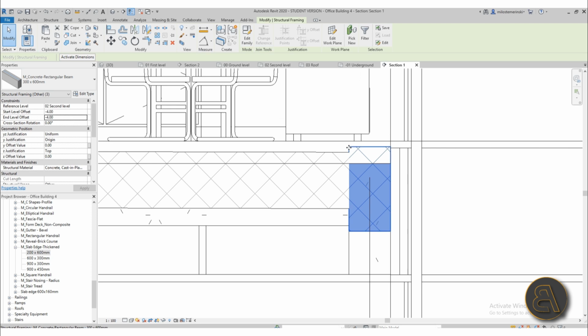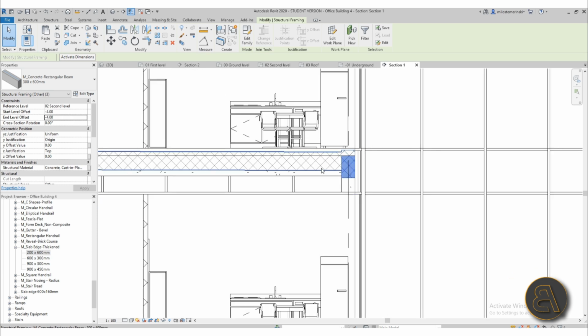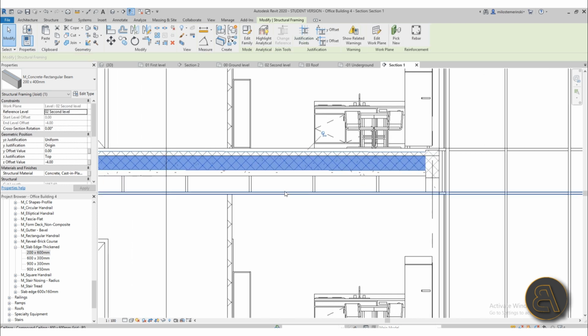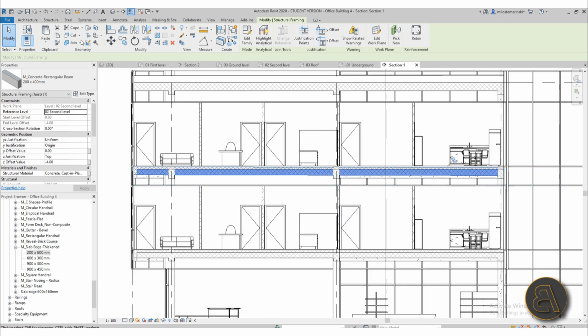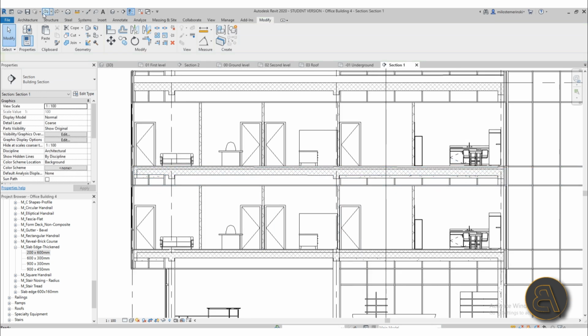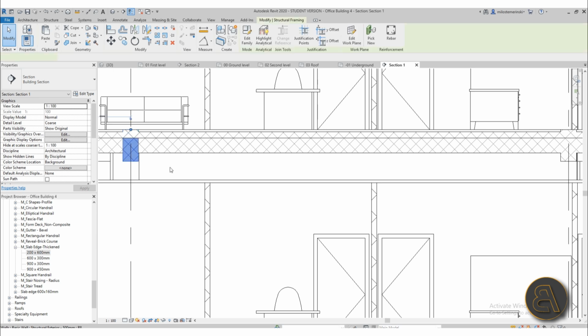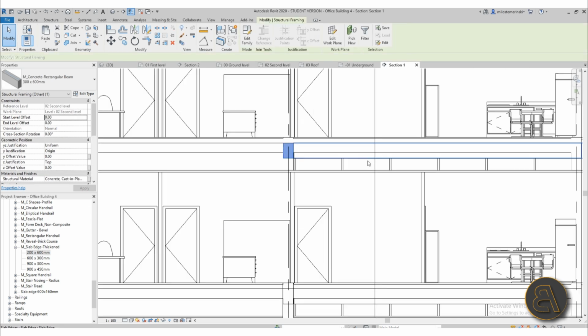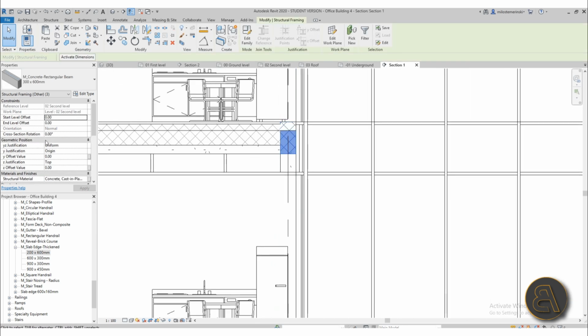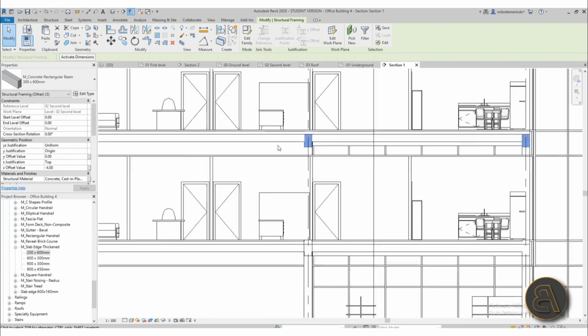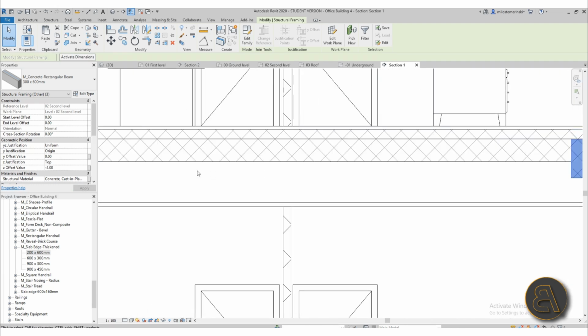Here, I guess because of some of the connections, it's pulling down these beams. So if you have a trouble like this, then I guess the solution could be to play around with that Z-axis offset. So let's try that. So here we have the Z-axis offset value, and let's change that to -4. There we go. Now it looks a lot better, cleaner.